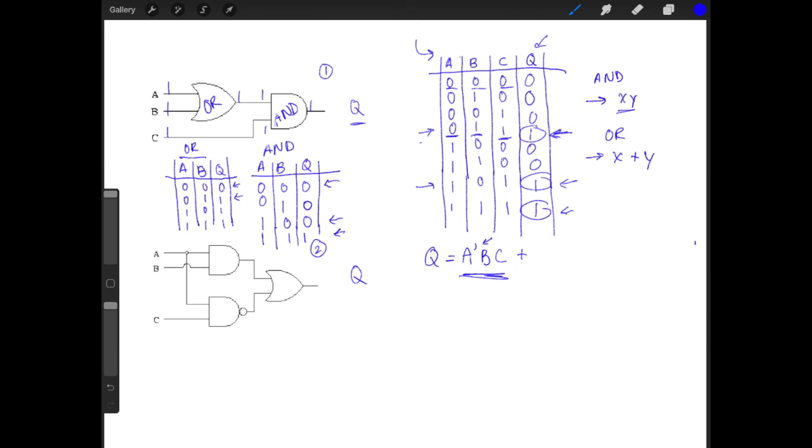So now let's write that out. So A is 1 when B is 0, so then we're going to invert that. So B prime and then C. Got it? So when A is 1 and B is 0 and C is 1. And then we have our last situation here. So when A is 1, B is 1, and C is 1. Got it? So we don't need to invert any of them because they're all 1s. So this will be our unsimplified equation representing